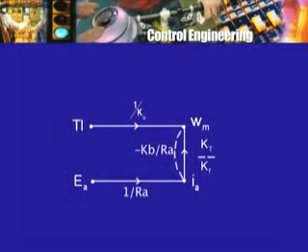Okay. So, now that we have drawn the signal flow graphs, we have put down in a graphical form all the information that we know about the system, namely the relationships between the various signals. So, now we can leave behind those equations and concentrate on the graph. Now, Mason, as I told you, gave a rule, or one can write it in the form of a formula, and it is called Mason's gain formula, because we will see that some terms that appear in the formula look like gains. These are the multipliers in any one of these blocks, transmittances.